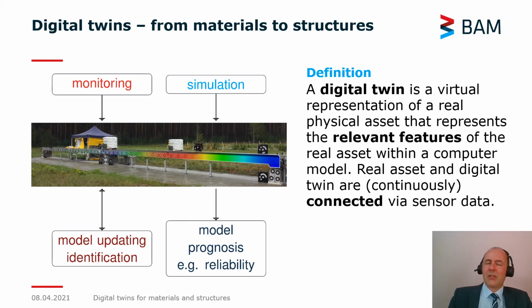Now, the question is, how do you incorporate this sensor information into changes of your model? You could, for example, just measure, I don't know, forces, and then use those forces in, say, a fatigue analysis. So instead of using predicted or estimated, I don't know, traffic densities, you could use the direct loading that the structure has seen, and that might improve the structural performance computation. This is, I would say, the first level of a digital twin.